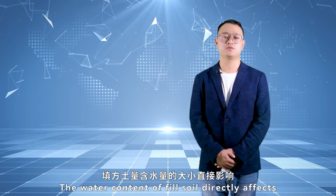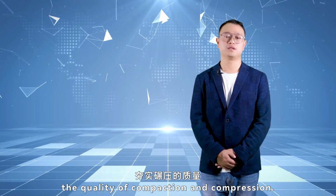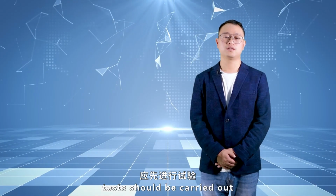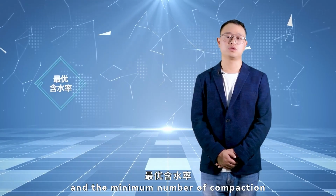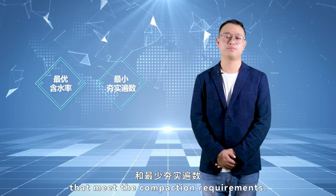The water content of fill soil directly affects the quality of compaction and compression. Before compaction and compression, tests should be carried out to obtain the optimal water content and the minimum number of compactions that meets the compaction requirements.